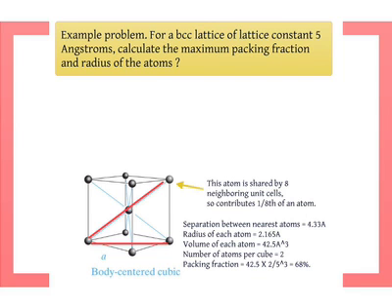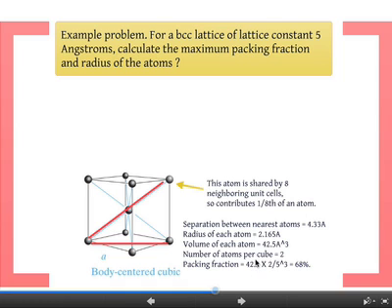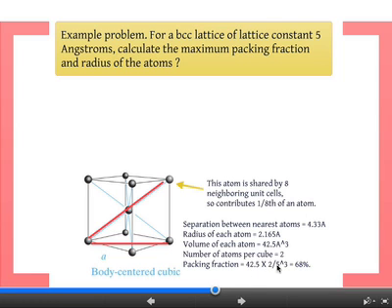So the packing fraction is how many atoms are there per unit volume. Take the number of atoms, which is 2, divided by the volume of the lattice. Sorry, it's actually my mistake. The packing fraction is the total volume occupied by the atoms, so 2 times the volume of an atom, divided by the total volume of the cube. So that represents how closely, how densely the atoms are filling the cube, essentially.